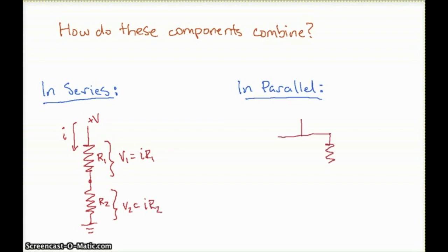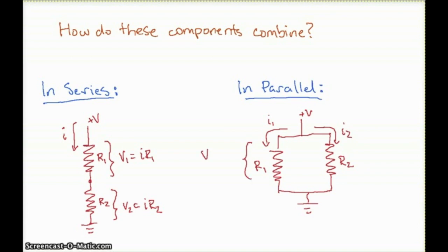In parallel means that you apply the same voltage across both of the components, but different amounts of current could flow through either one. The current through either resistor is determined again by Ohm's law.